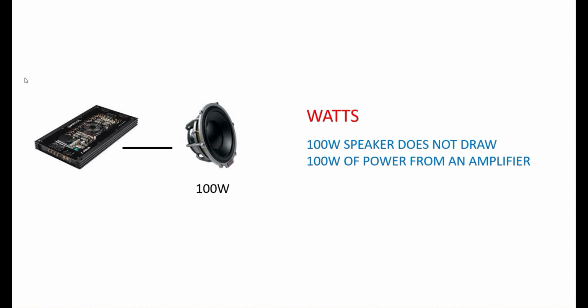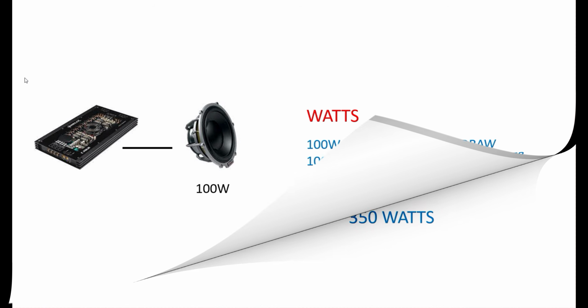And of course, the wattage to the speaker is always going up and down. So if you're running your system and listening to it daily, it's unlikely that you'll be sending a full 100 watts to the speaker. That would be super loud. It's probably more like 20 or 30 or 40 watts, for example. It really depends on the loudness and the impedance of your speakers.